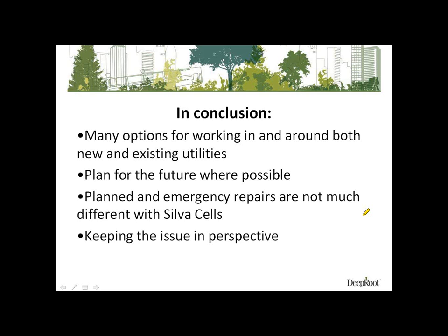To optimize the largest opening we can get versus the strength. So there's been a fair amount of engineering that's gone into that. And the aperture on our recommended geogrid is up to, I believe, 1.25 inches. So you have a 1.25 inch by 1.25 inch opening. It's a fairly large size opening, and then that also stretches to larger than that.